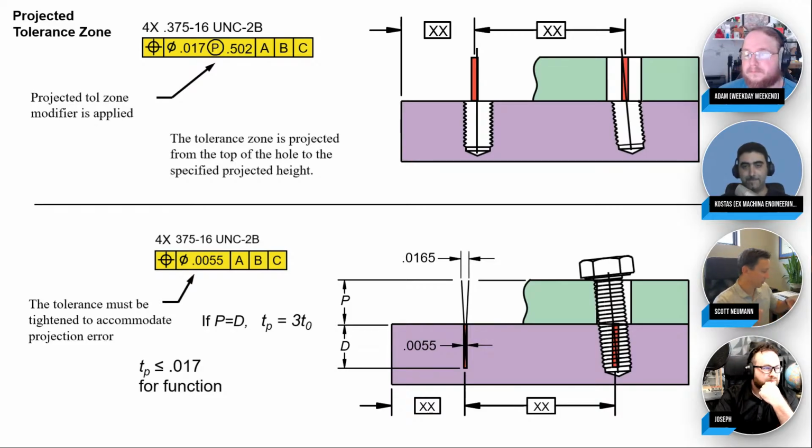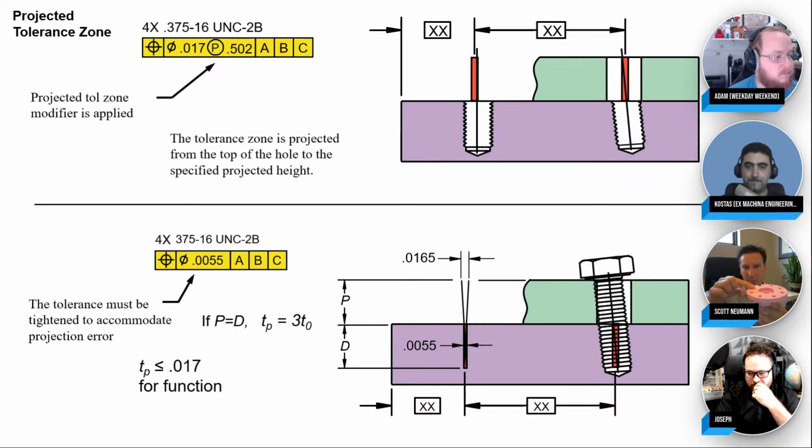Inspection loves it too, because let's say you have a part that has some blind tapped holes in it like this one. So let's just say these are blind tapped holes going into the part. How do we check it at the height of the part and then sticking out? Oh, just use a thread gauge. So stick a thread gauge in there. I got a couple thread gauges. Yeah, there we go. I got a few of them here. There's another thread gauge right here.